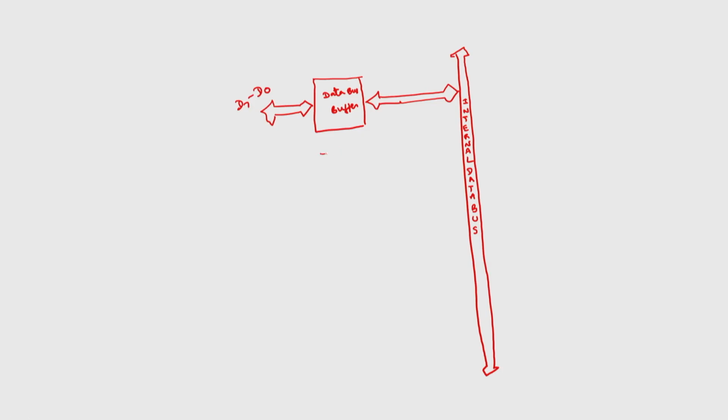Then we have read write control logic. This is also bidirectional. Some control signals are input signals and some are output signals, because it can read or write memory as well as IO. What are the different signals? The very first signal will be chip select bar. You have to first select this chip using some address decoding logic.